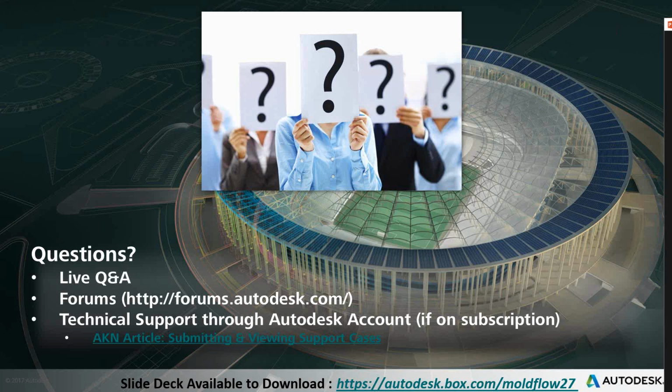I've played around a bit with the geometry parameters and what you can move. If the CAD is not watertight, right, it's going to be a problem to mesh. And doing the moving of the geometry may be a problem.